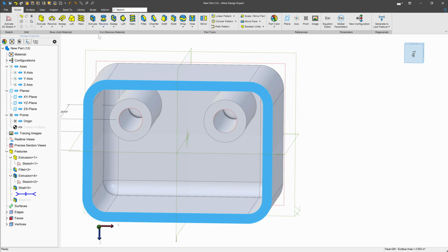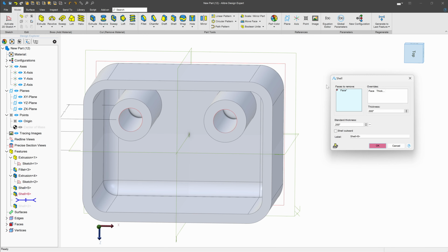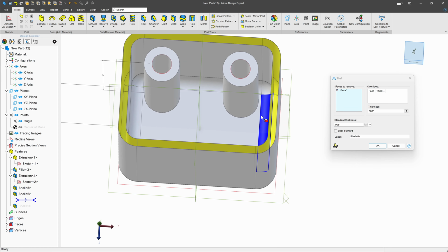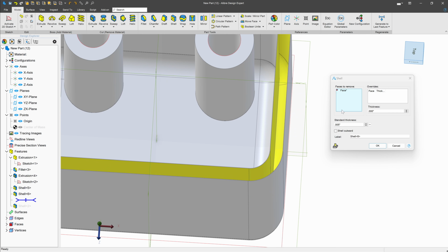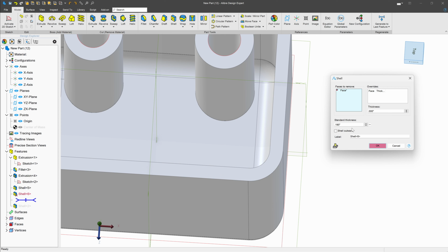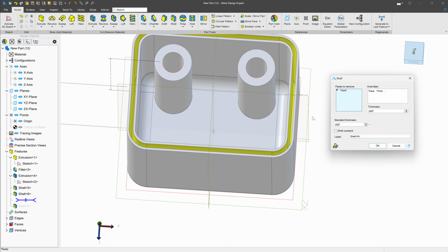For instance, I'll take this face, and if I shell it, and I do a thickness of 0.001 or maybe 0.005, right? If we go really tight, well, now you have one part fit inside another part at a definite tolerance. So if I say 0.19, oh, I should probably say 0.9. Right, well, we can find the dimension that works, but you can get parts to fit inside of other parts that way pretty well.